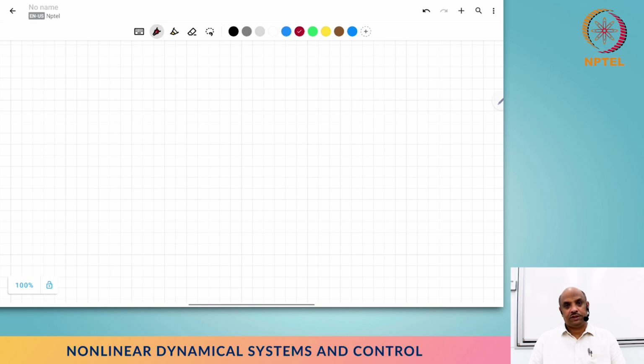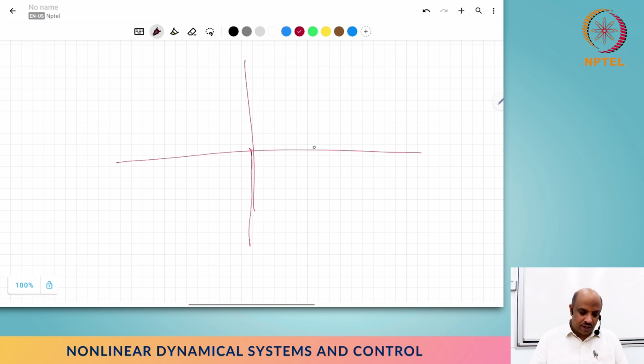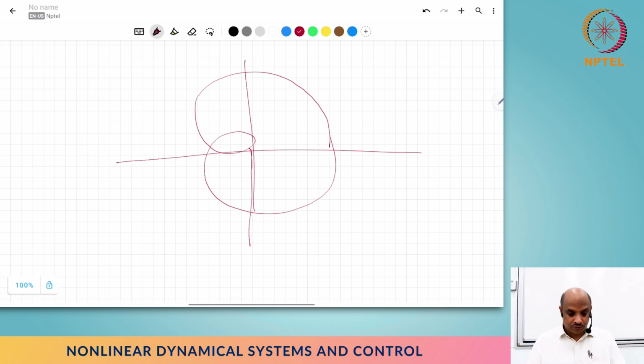But when it comes to stability margins, which is essentially looking at an uncertain problem, we will see basically how we cross this point -1. In the scalar case, it becomes -1. In the multivariable case, let's say this is my Nyquist plot. Say here we are dealing with delta G, a square matrix, and we will imagine that we basically draw eigenvalues of each of those things and pretty much draw the Nyquist plot. Let's say this is -1.